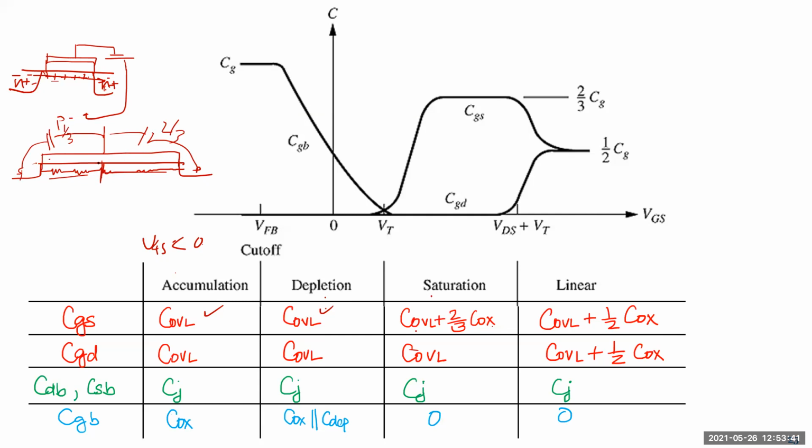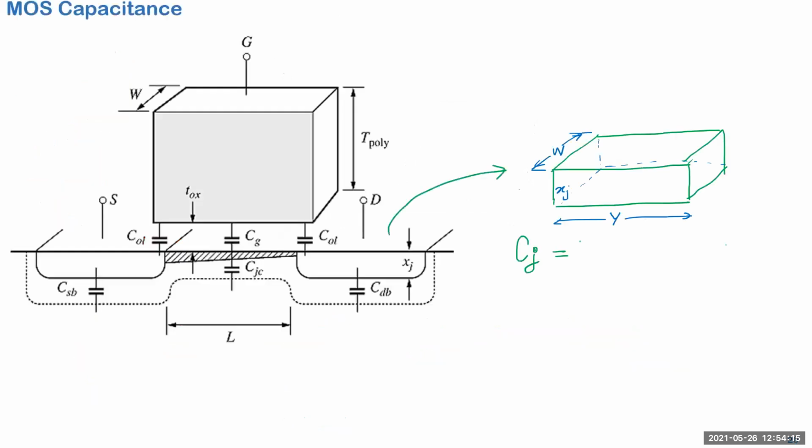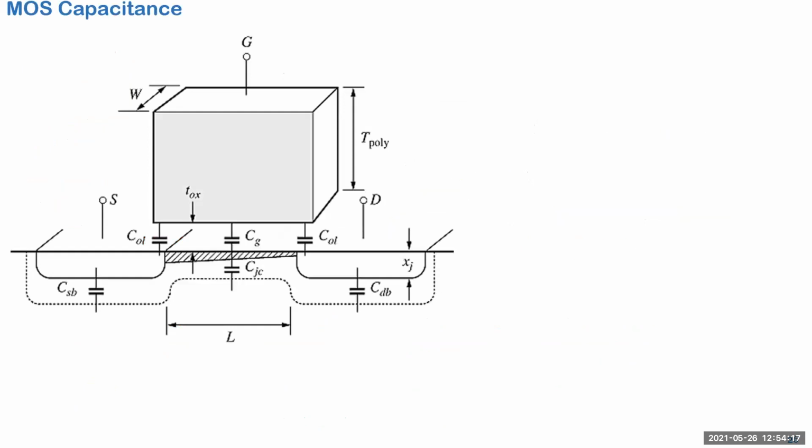But if your operations are in hundreds and hundreds of gigahertz, you have to use what's called non-quasi-static models, NQS models, because in the quasi-static model we use, this resistance is actually 0. So the partitioning might be off, but it's the most convenient one for the modeling we are doing. In a real non-quasi-static model, the channel is represented properly, so you don't have any issues.